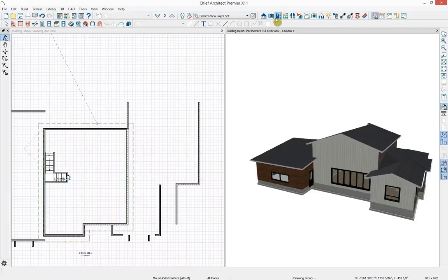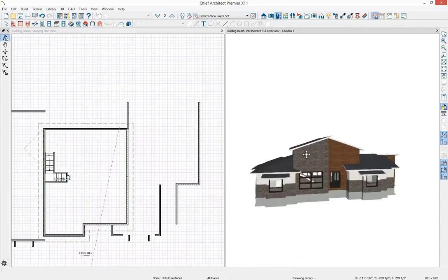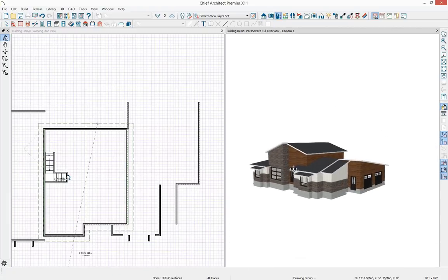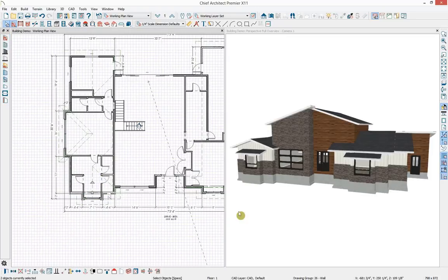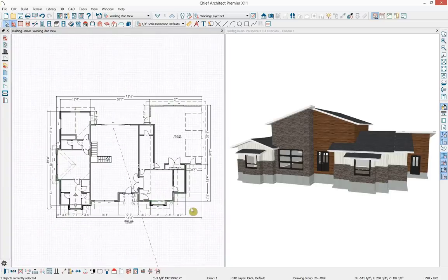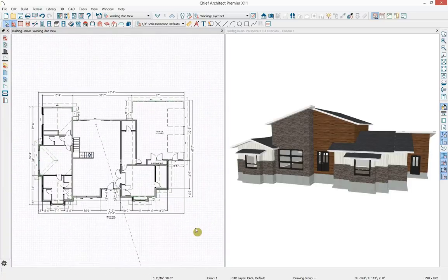Alright, so now let's swing back around to the front of the house and just make sure there aren't any more changes I want to make. One more. We just need to change these 2 walls to gable as well. Alright, so those are the last automatic changes we're going to make, meaning the last ones that we're going to use the walls to edit the roof planes.